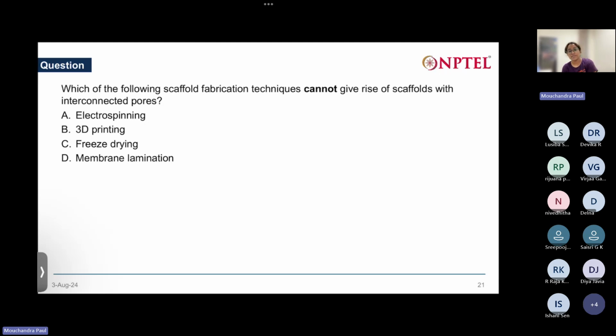Okay. Then freeze drying, or it is also known as lyophilization. So here what happens, you first freeze your sample, so whatever water content is there turns into ice, and that solid frozen sample is dried under very low vacuum and very low temperature.